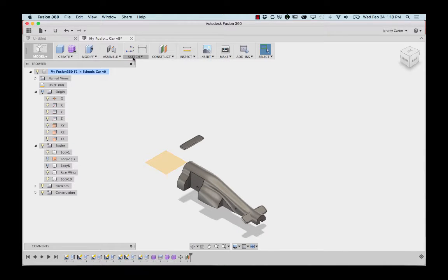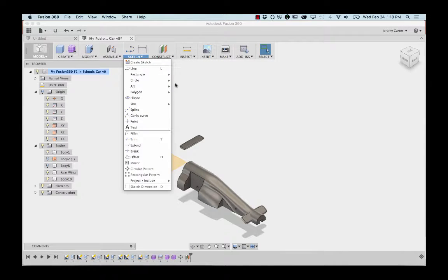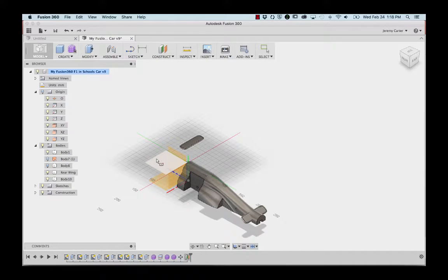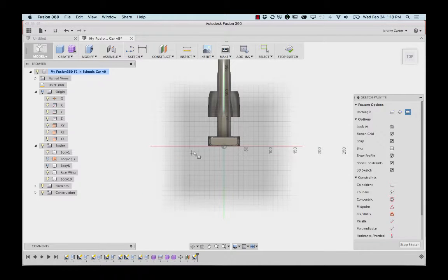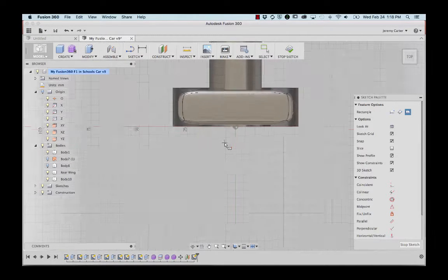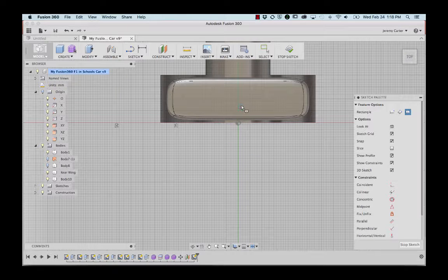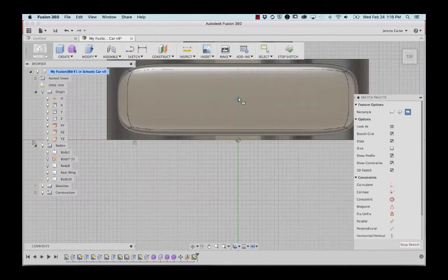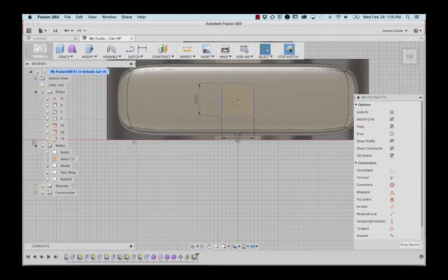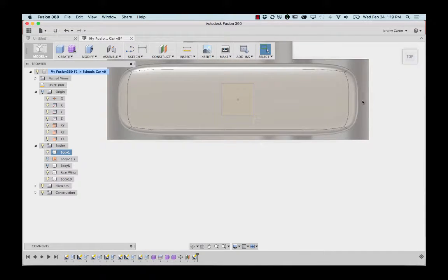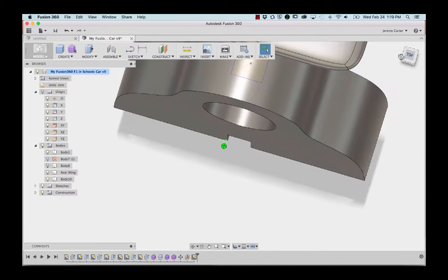Select the center rectangle sketch and choose the plane we've just created. Select the center of the wing to position the first point and make an 8mm by 8mm square. Click Return. Stop the sketch. Now you're going to create a support on the wing. Create another offset plane 100mm from the ground plane.